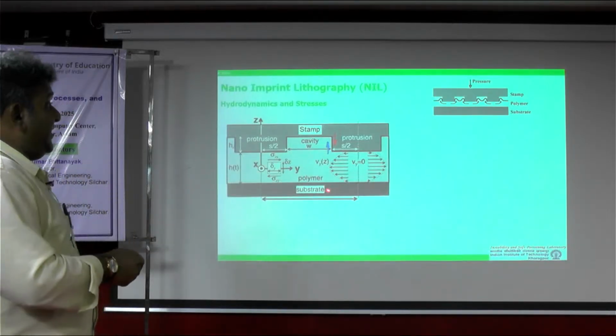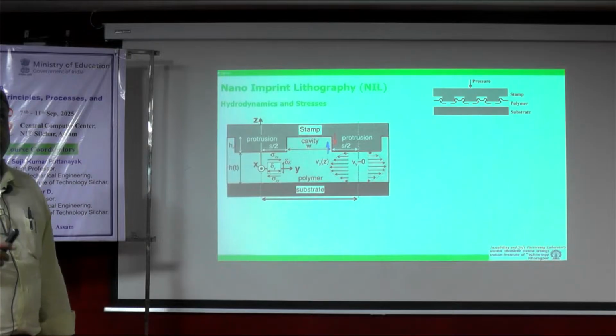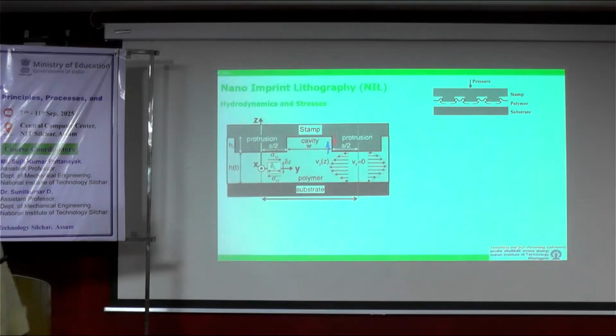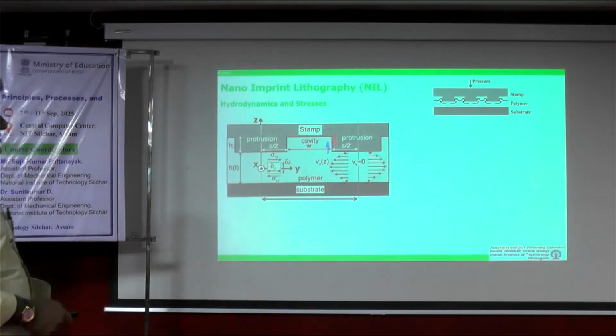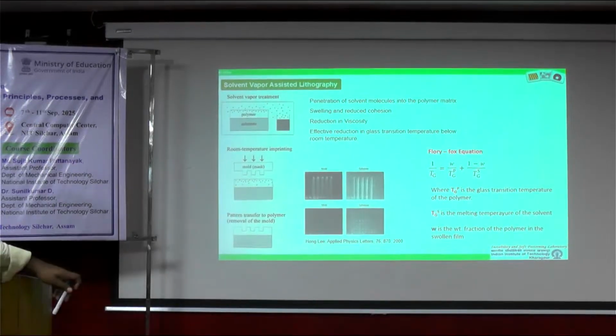So basically, these patterns that are created by nanoimprint lithography have a tendency to contain a lot of residual stress, which is not very good, because subsequently the material tries to release this stress, which can lead to pattern damage and associated problems. There is another way of achieving the same effect, and that is by solvent vapor exposure.